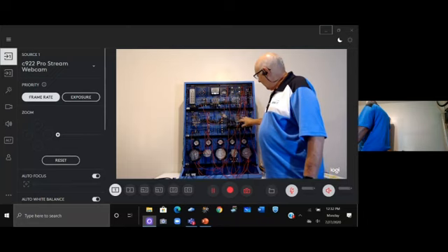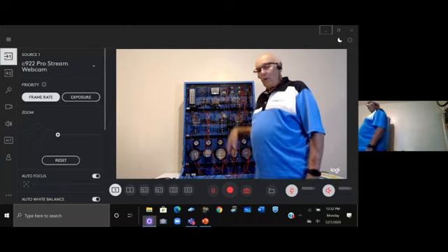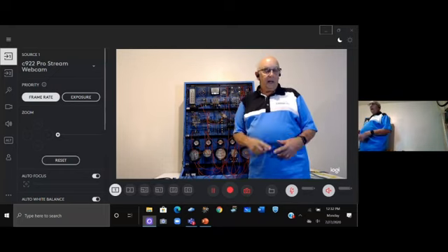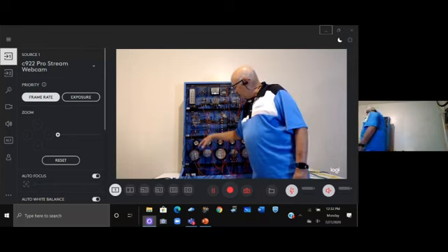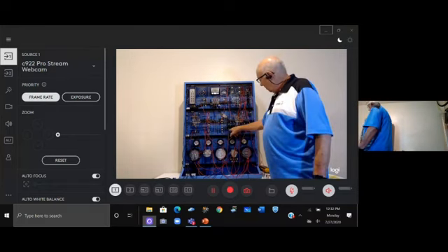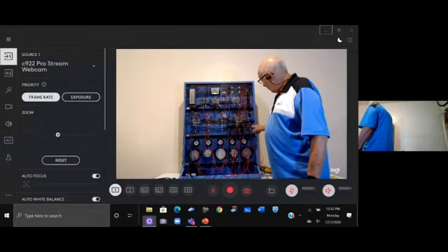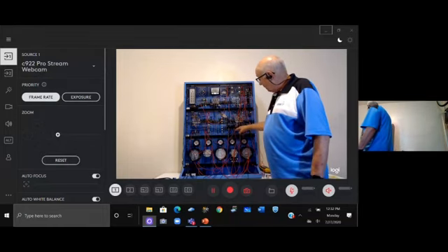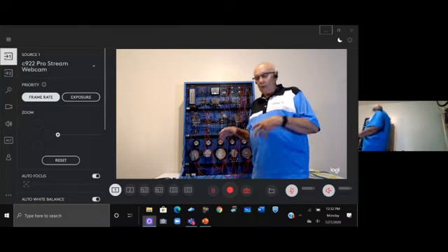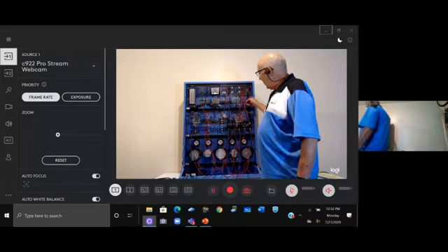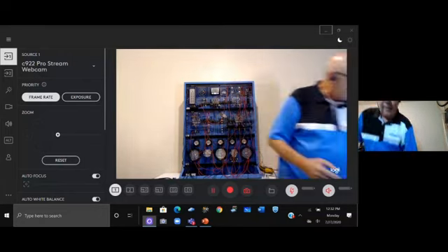And we have an output module over here. These need to communicate with one another. Now, one of the things I did in an effort to be able to make this a 2-hour class is I have wired the loads. So if you look over here, and you'll get a little more close-up, I have 5 terminals: right turn, left turn, backup, marker, and tail lights. Okay, so those are coming off the output module, and the output module has fuses on it. Okay, so let me go back to the PowerPoint.